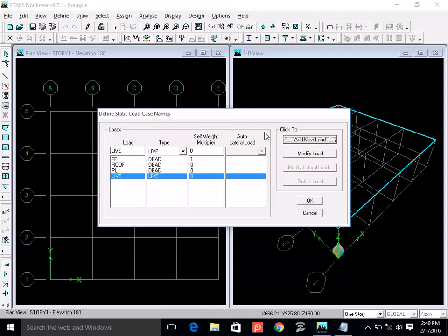For a classroom it's different, for a hospital it's different, for a corridor it's different, for a warehouse it's different, right? So you can use those values, but all of them are actually live load. The generic is live, so you don't have to define multiple live loads. And it includes furniture, not just human beings. For example, if the load for the classroom is a specific number, say 60 pounds per square foot, it includes human beings and furniture and fixtures, whatever it is.